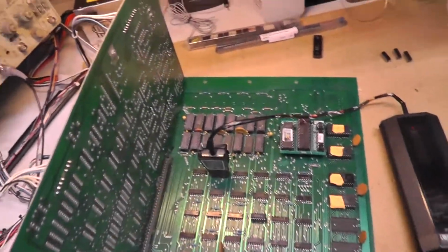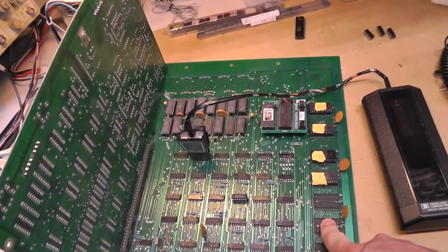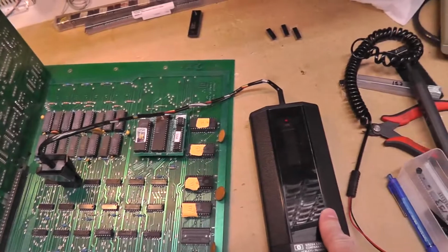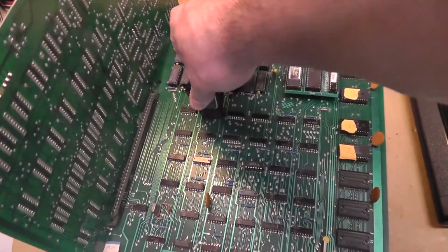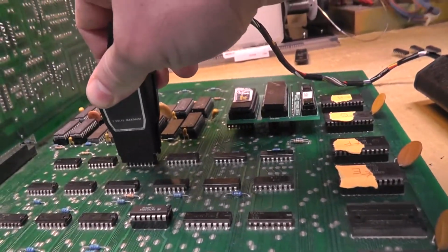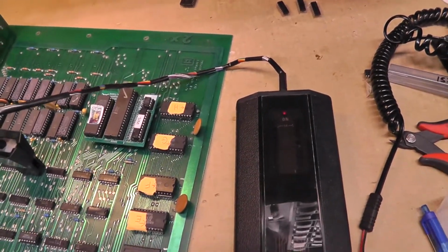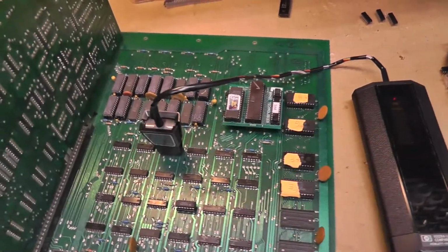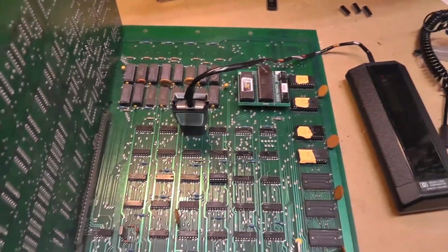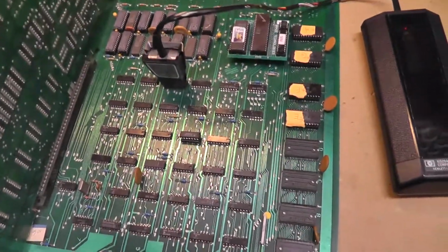Alright, just to make sure, because I was probing around off camera, I went and got out the other board that I was working on, and it also has 9322s in there, and my logic comparator looks good. I can get this on there right. Yeah, you can see there's no weirdness going on. So I guess I will go ahead and replace those. I also found something else wrong with my other soundboard, but I'll come back to that later.